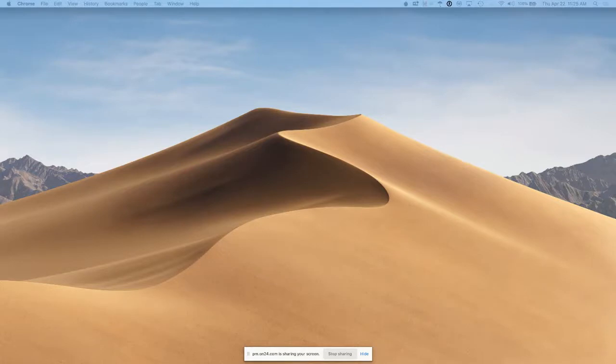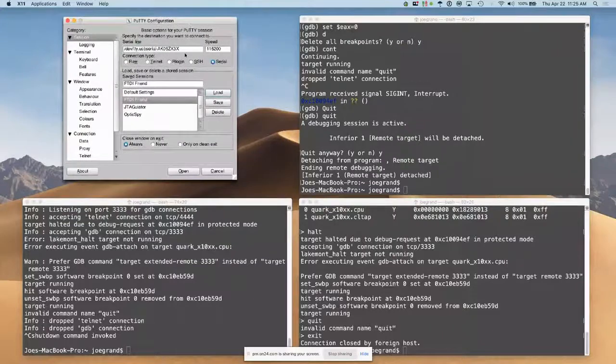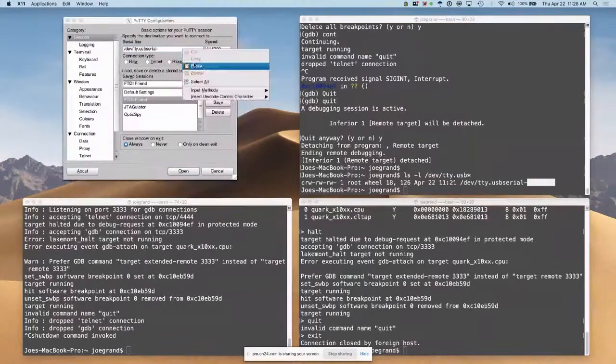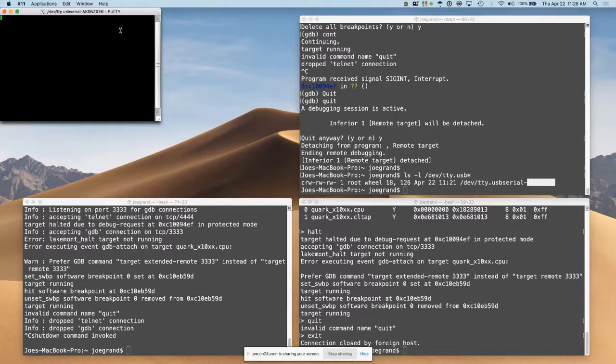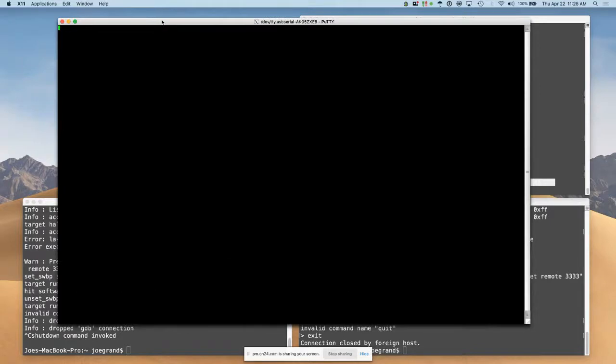Okay, so CoolTerm seems to not like things anymore. I'm going to switch over to another view. I have a terminal program here called PuTTY, and I should be able to use that to also communicate to the USB to serial device. I just need to check what the COM port is. Okay. So let's see if this one happens to work instead. Right, so I have my serial port set up, FTDI friend. Let's see if we can open. See if I can make this a little bigger. I don't know how small the text is going to be.